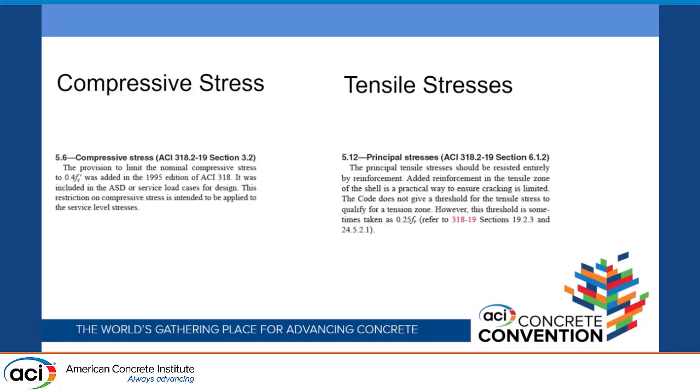So we talk about compressive stresses. We want to keep them low. Tensile stresses, we resist them entirely by the steel, but we also have requirements in there that the spacing of our bar has to be tighter than a normal concrete structure because the cracking is very critical.